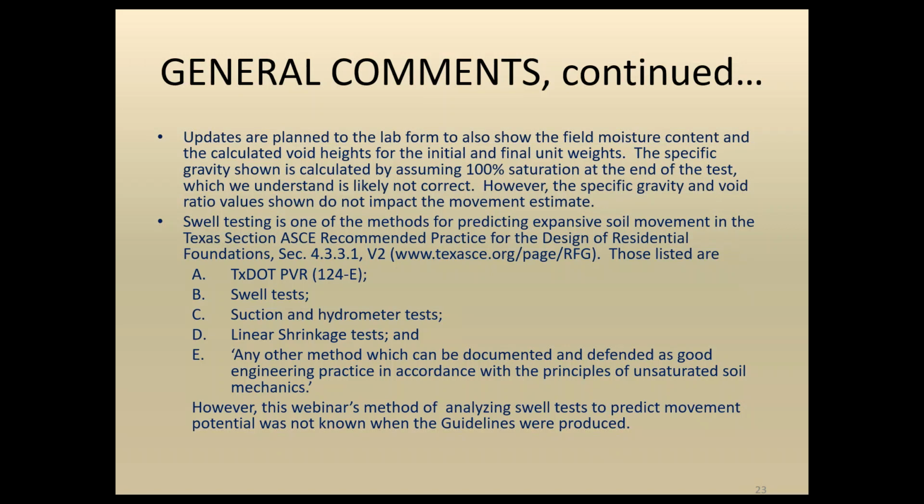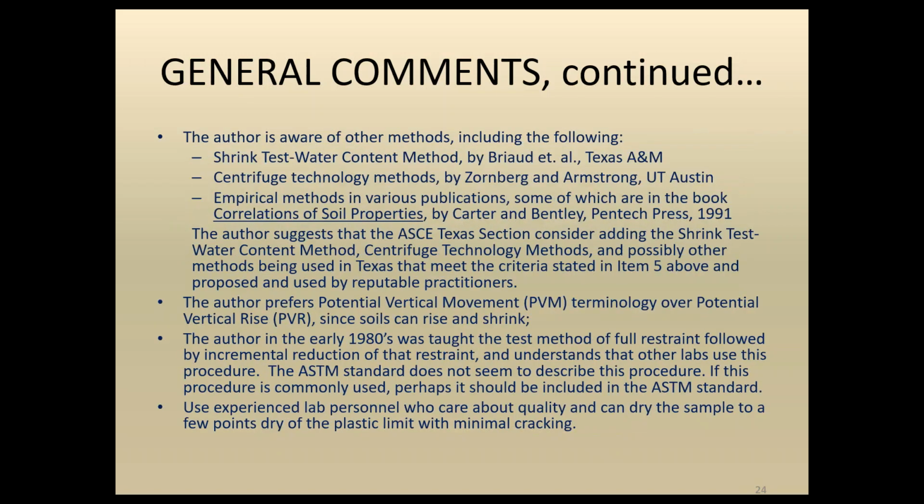So the methods that are shown are the TxDOT PVR method, swell tests, suction and hydrometer tests, linear shrinkage tests, and any other method which can be documented and defended as good engineering practice in accordance with the principles of unsaturated soil mechanics. I do want to note, though, that the method of analyzing swell tests presented in this webinar to predict movement potential was not known when the guidelines were produced.